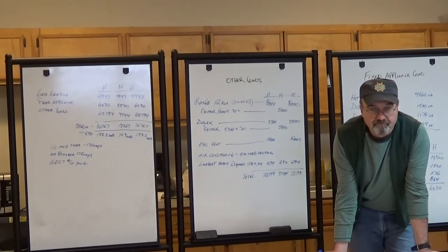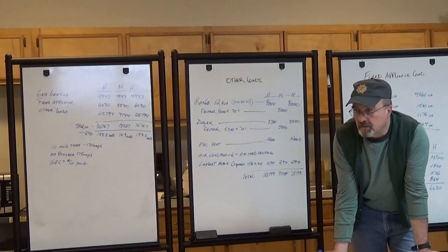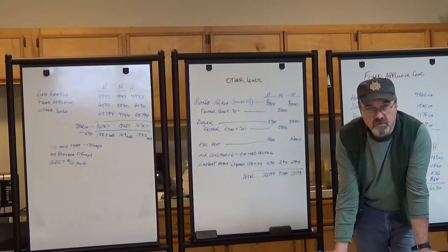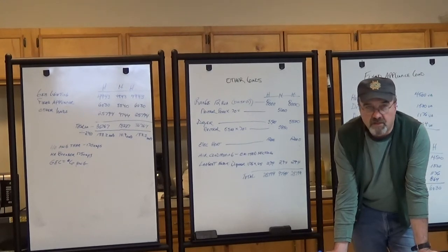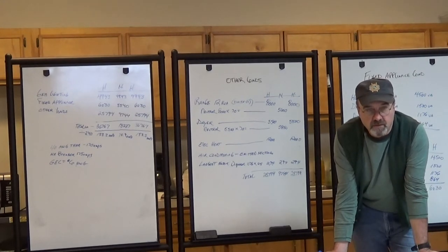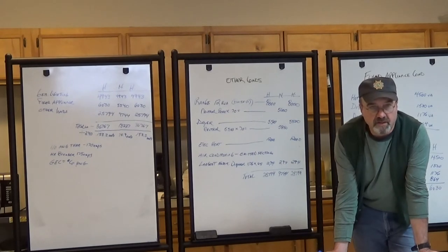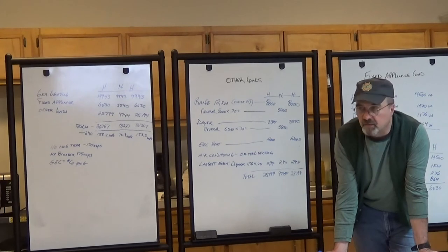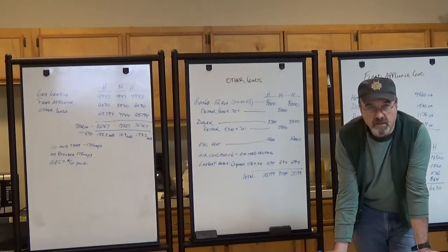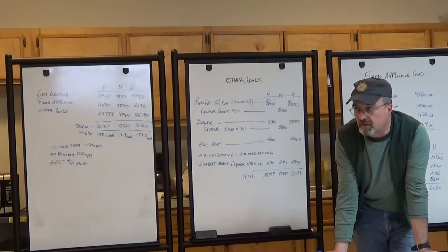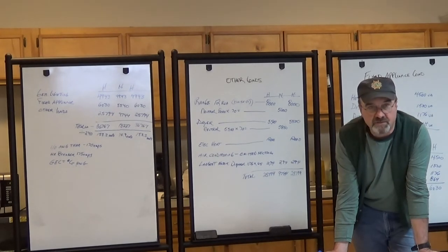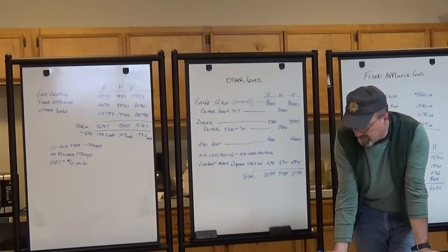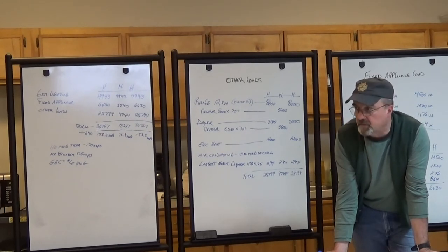Now, as electricians, it's good to oversize a little bit to allow for future growth. The owners of the house may want to install a swimming pool, enclose the garage, or add on to the house, so it'd be good to have a little extra capacity in your panel board and in your service entrance conductor calculation to provide for that. But this is the minimum that we have to have, okay?